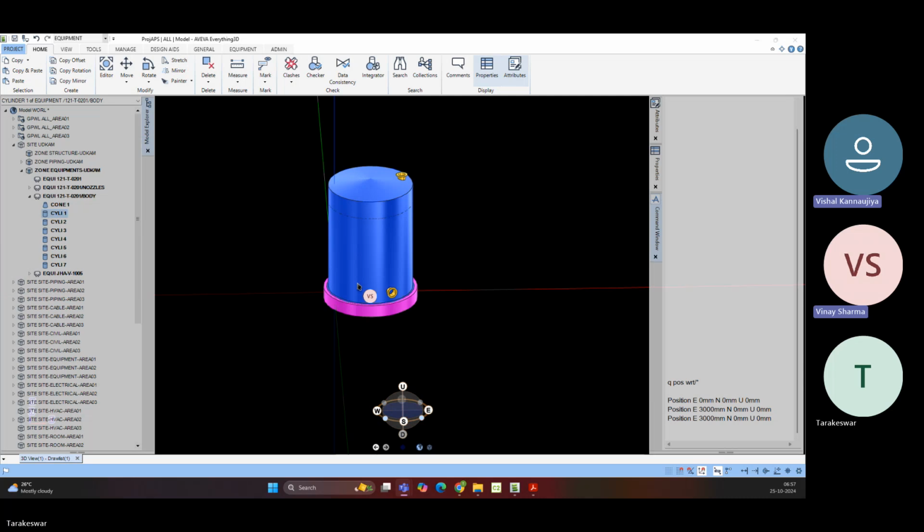In that case, it will not come in that report. For example, some bends are there in slope lines. If you put it as non-reportable, it will not come into the report. But actually, those things you require on site, so for that you need to give it manually. Understand?